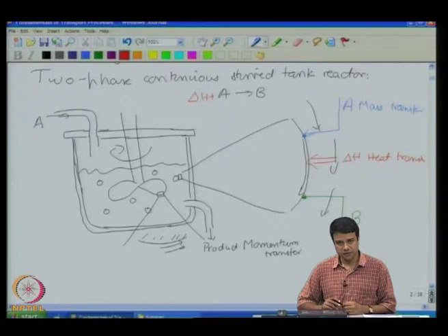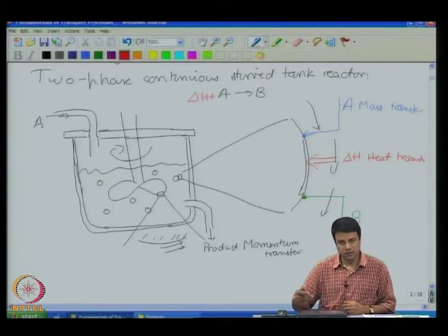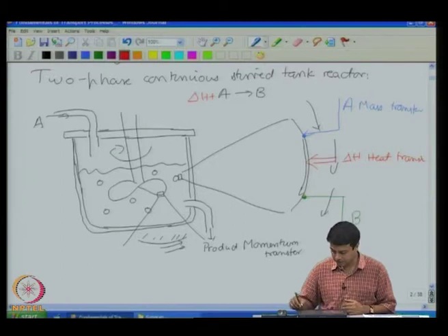If you look closely at the surface itself, the fluid flow does not penetrate the surface because the surface is an impenetrable surface. Therefore, the fluid flow has to be tangential to the surface. A fluid flow tangential to the surface is not going to transport mass or heat to the surface. It is going to transport only along the surface. For the mass to go to the surface, you need to have transport that is perpendicular to the surface. That transport can take place only due to diffusion. So, ultimately there has to be diffusive transport for the material to be transported to the surface.